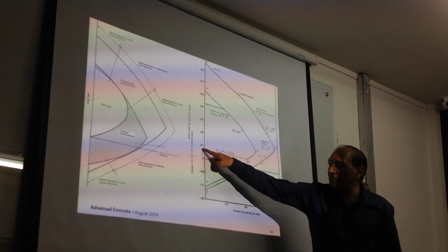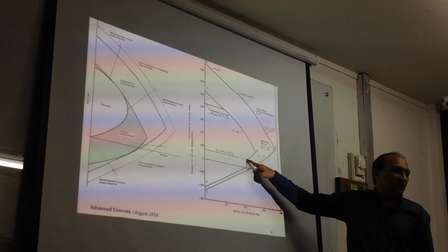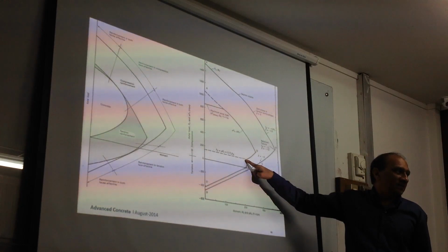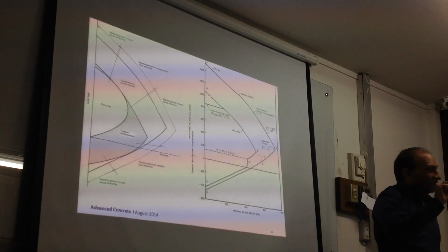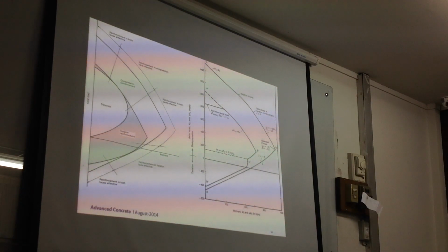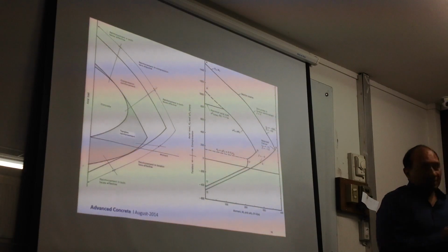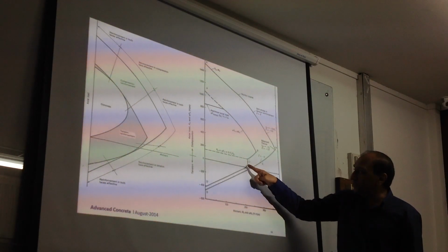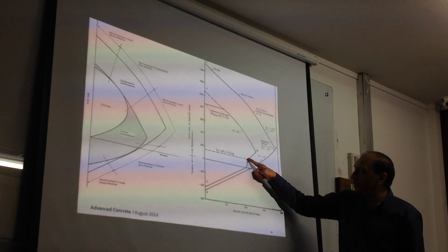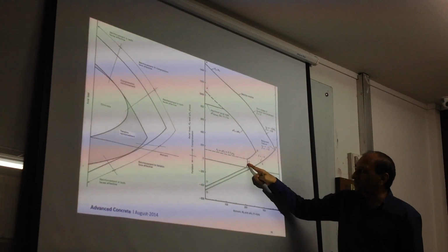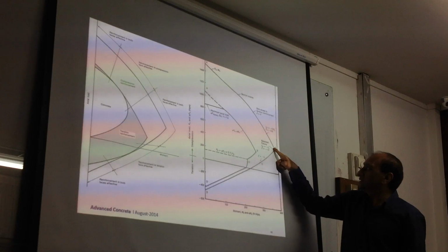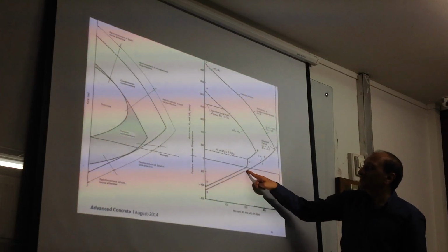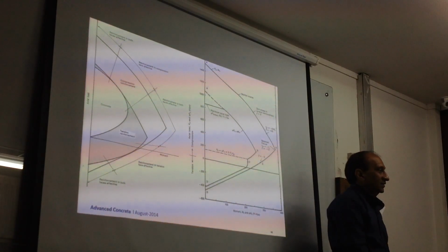So if you draw the line at 10% and you cut here, the phi factor changes here. The phi is 0.9 for beams, for columns it is 0.65 or 0.7 or 0.75 depending on the dimension. Right? So those things, and here as you can see, the phi factor is different, you get a different curve, and then this is without the phi factor, you get another line.